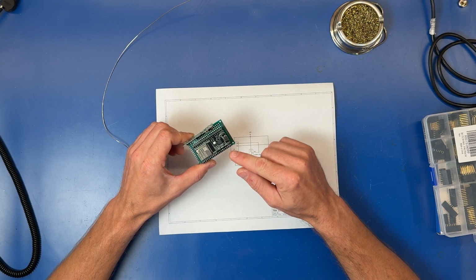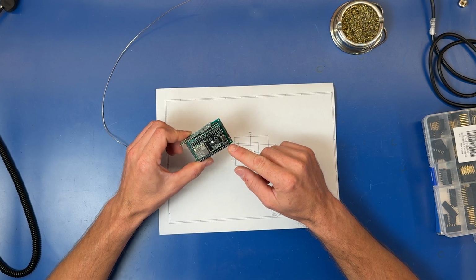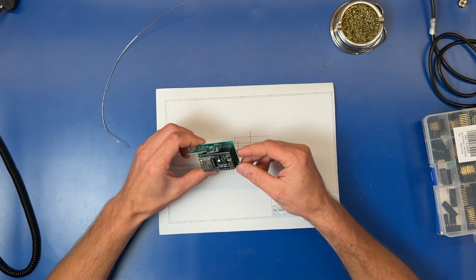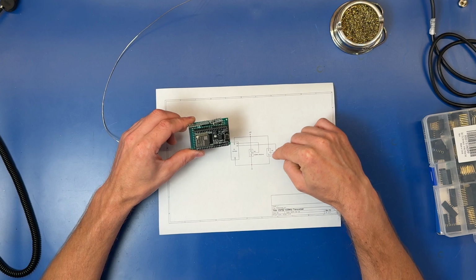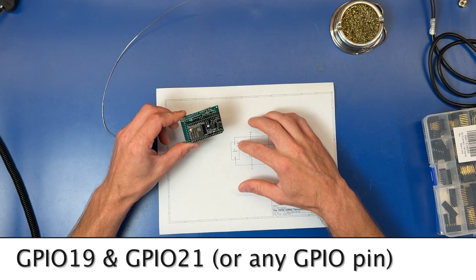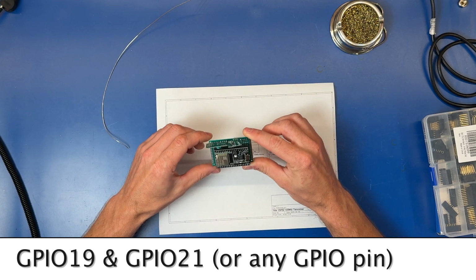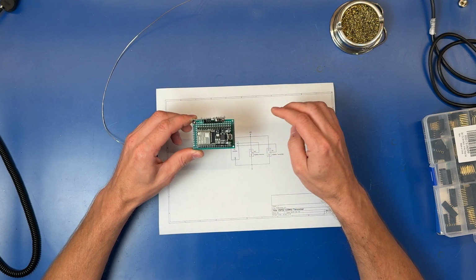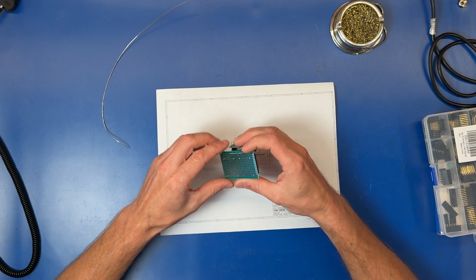ESP32. So basically ground is right here, and we also have positive 5 volts right here, so we'll wire that up to that. And then each of these modules connects to D0 and D1. Those are the pins that I've chosen for this, but we'll see if we need to update any of them. So yeah, let's go ahead and start soldering all the connections.